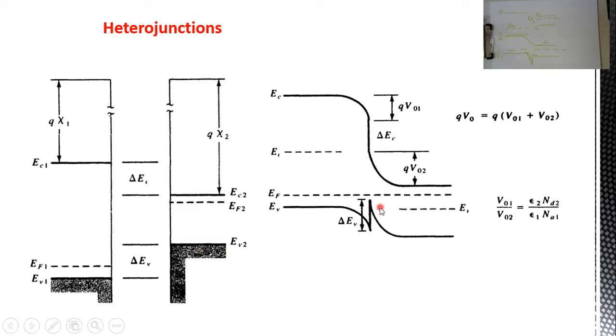This is simply because in this region, as you know, holes' energy is decreasing upward. So automatically holes will be accumulated in this spike, because any hole here will automatically go there. But holes will never be able to pass this barrier.